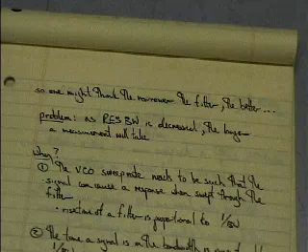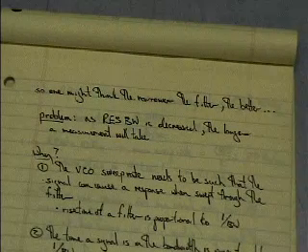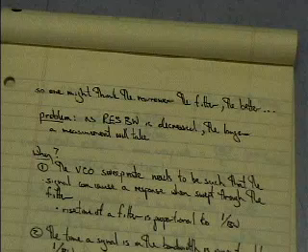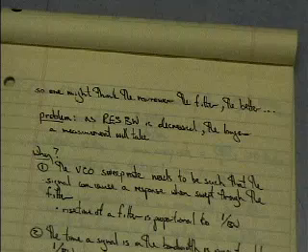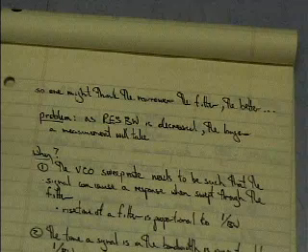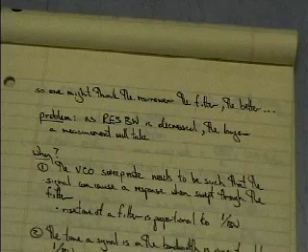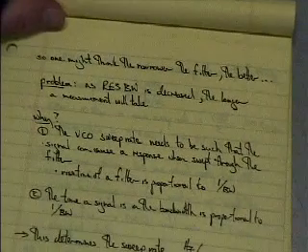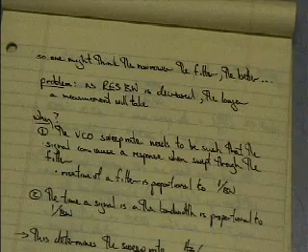If you have a filter with very high bandwidth, it will respond very quickly. A filter with very low bandwidth is going to respond very slowly. If I'm sweeping a signal through it, the signal is going to have to stay in there longer for it to respond. And the bottom line is that the res bandwidth is going to determine the maximum sweep rate.